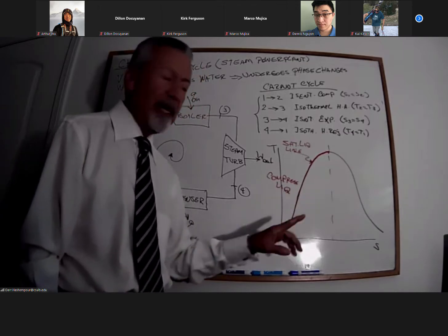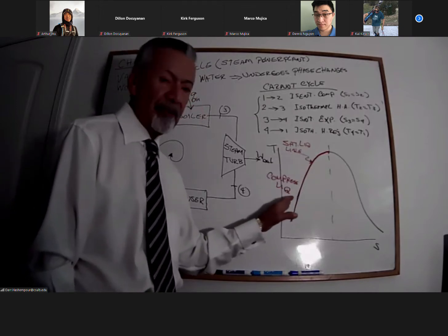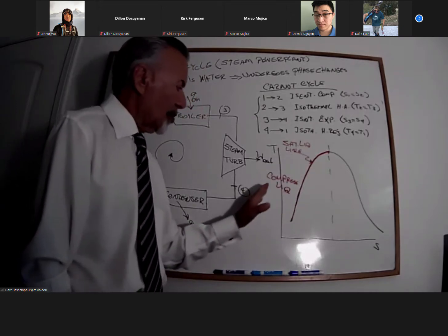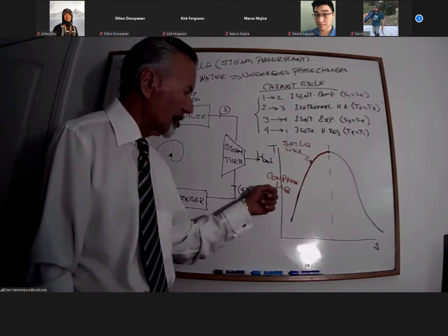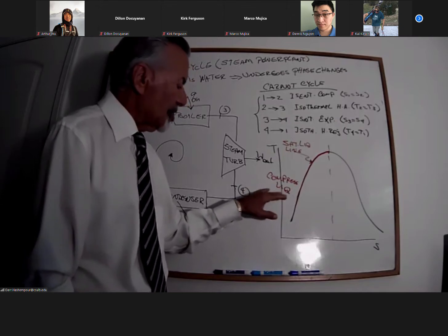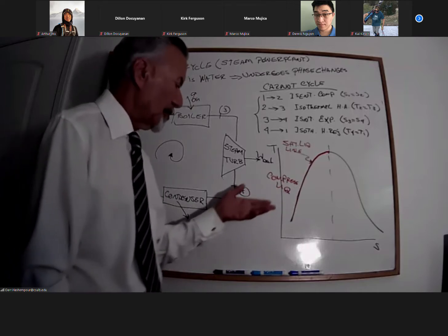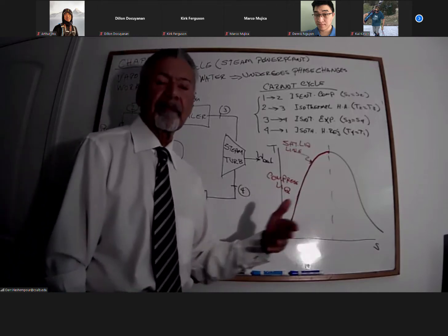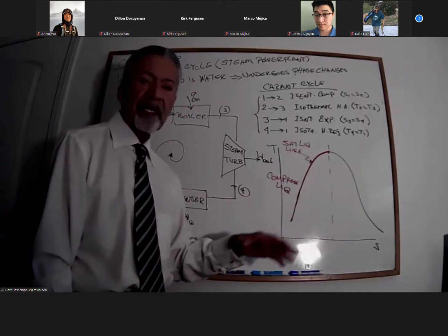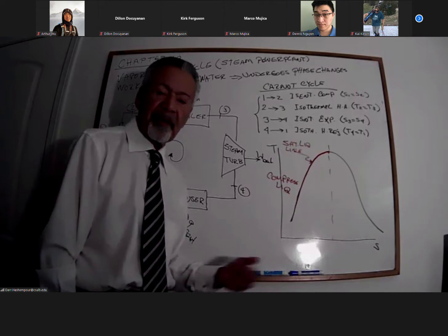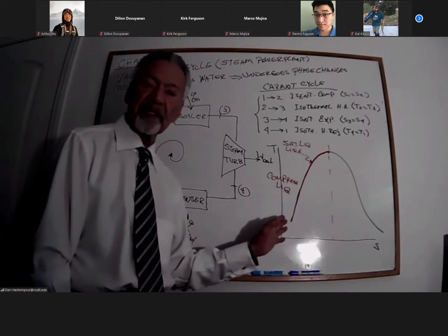There is only one table that has all saturated liquid, including compressed liquid, because when we tried to create a table for compressed liquid, we realized the changes between the value of enthalpy or entropy or any thermodynamic parameters and those of the saturated liquid are almost identical, with a very, very small percentage of difference.